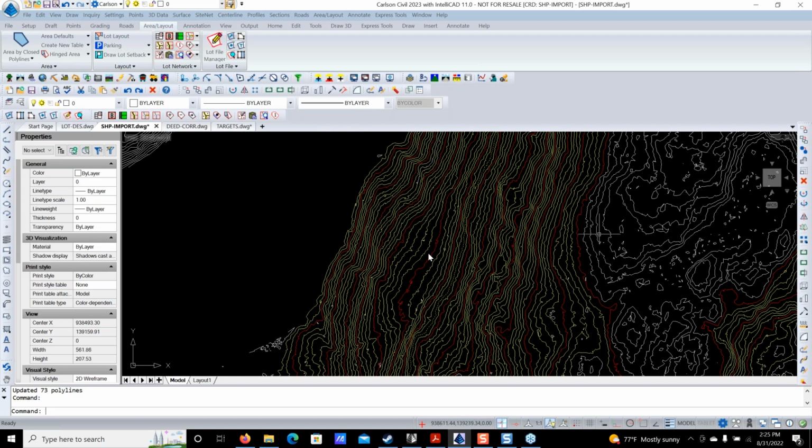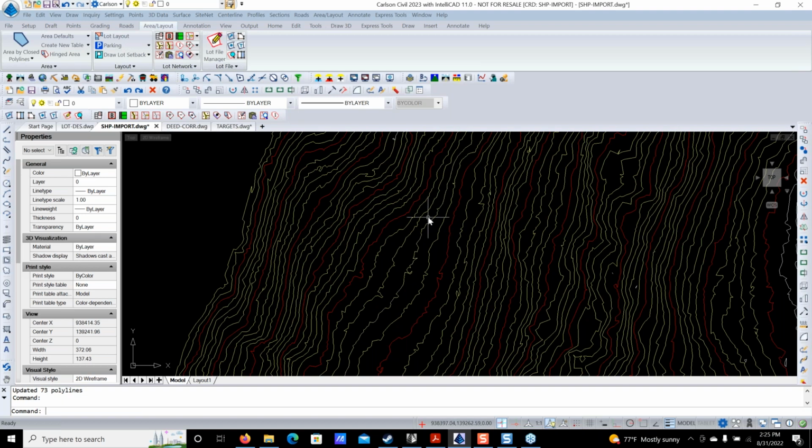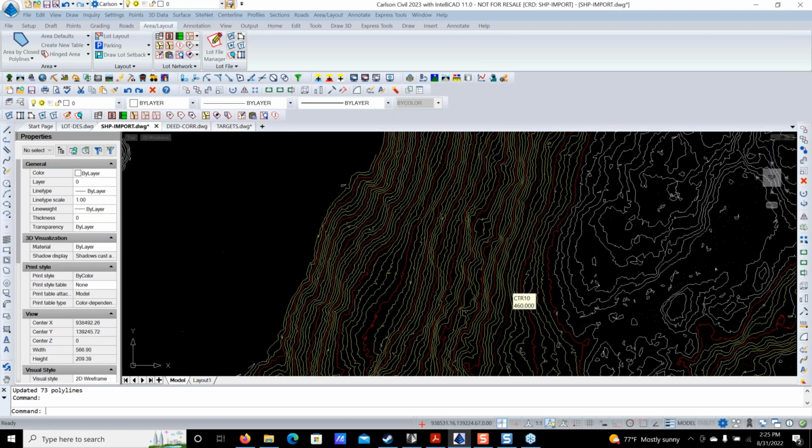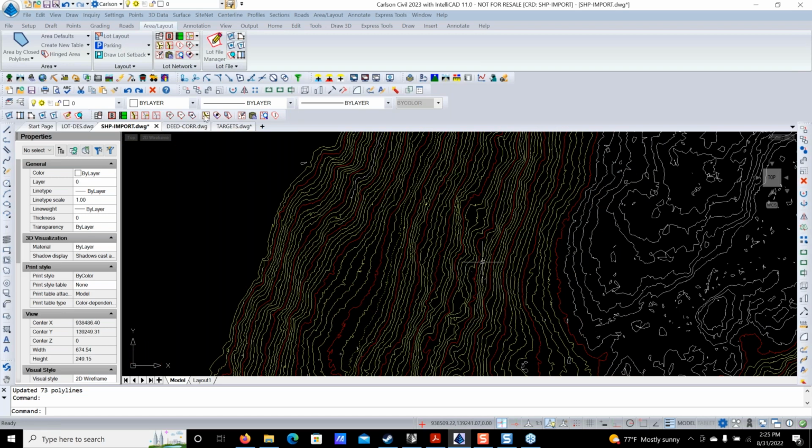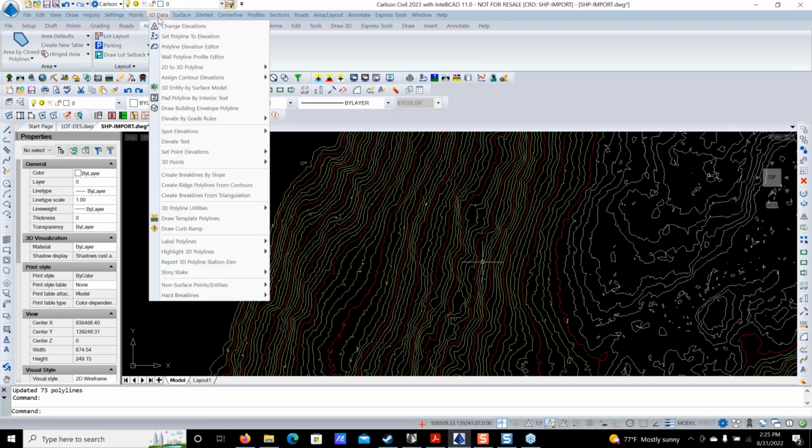And what happens is, practically instantaneously, it elevates all these contours, and it puts the intermediates and the indexes on 2 different layers. And that's kind of cool. So whether you're coming in from PDF or whether you're coming in maybe with a shape, but you don't have elevation attributes, which you may run into. I wanted to show you this tool, which is again, Ben, this is 3D data, assign elevate contour multiple in series power tool. A dramatic one here.